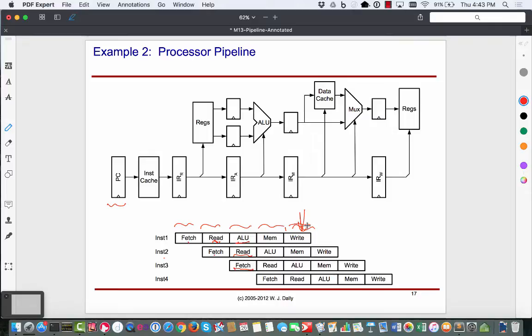Even something trivial like I mentioned that multipliers are often pipelined. So in many processors, if you do a multiply, the result of the multiplier is not known until 2 or 3 clock cycles later, because that's an indication that there is a deeper pipelining going on out there. So pipeline creates this kind of unfriendliness, but that's the only way you can deal with it. If you're using pipeline to push the speed up, then that's the penalty.